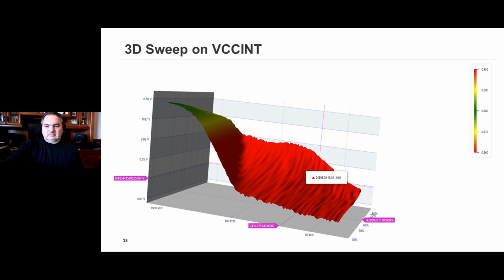This is my favorite slide. And I'm kind of glad Rob finished at the right time, because this is the slide I wanted to talk about. We've talked a lot about non-linearities and these pseudo-random events that can happen because of a multi-phase solution, which is only exacerbated with random or pseudo-random load current profiles. So there are two major tests that we perform to spot weaknesses in a power supply or a PDN quickly, whether it be the controller or the caps or whatever it is down the PDN.